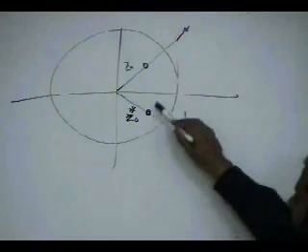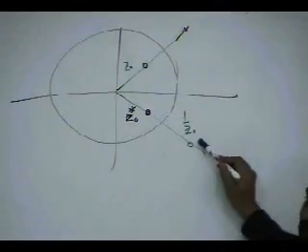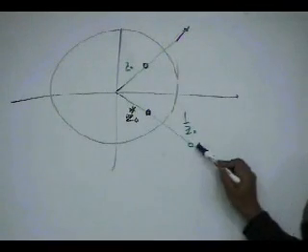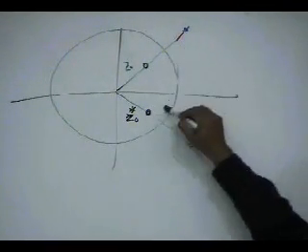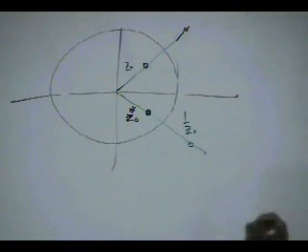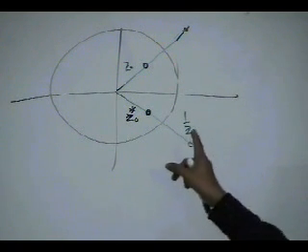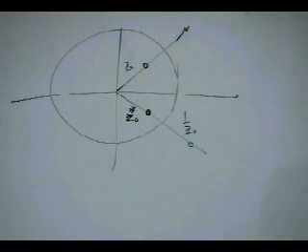Okay? This 0 is because the h of n is real. This 0 because this is linear phase. And this 0 is because it is linear phase. So zeros will always be paired like this. Okay? This is the consequence of symmetry, because linear phase must be symmetric. If it is symmetric, then zeros will always be placed like this. This is number 1.